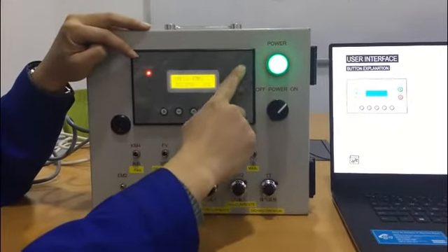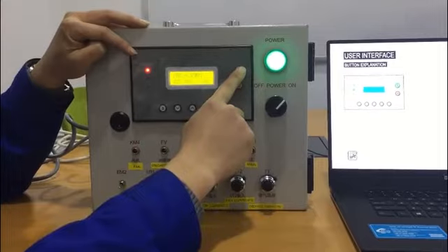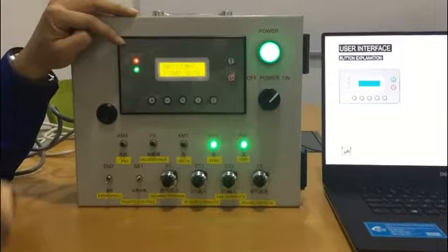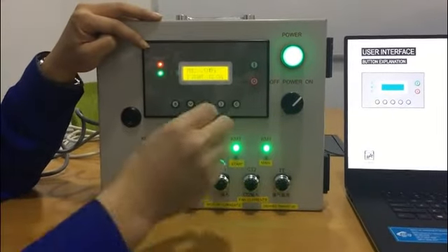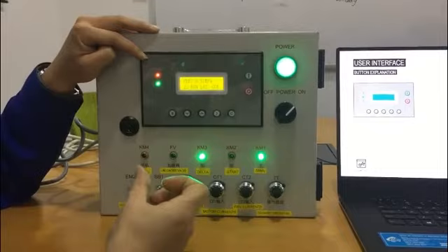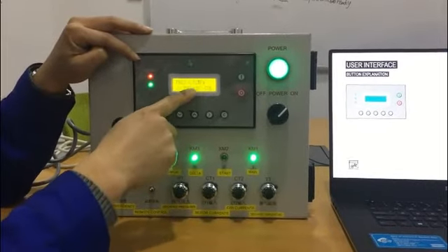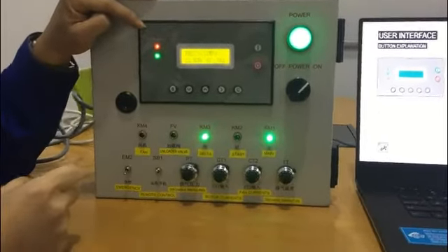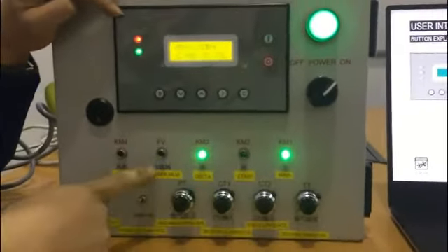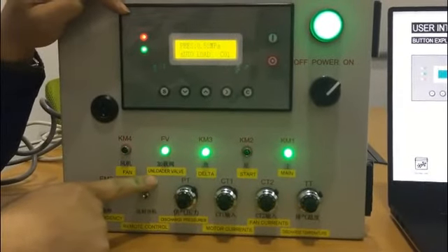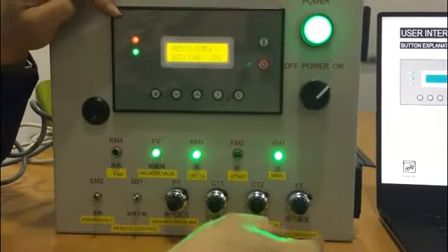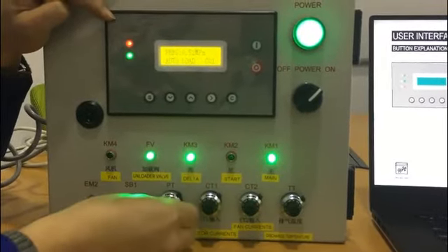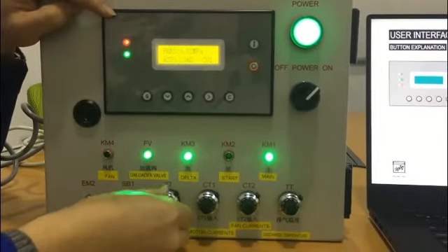And start the compressor. Press the start button. And there are 6 seconds for start delta change, and another 15 seconds for loading delay. Okay, it's in load. And if we turn off this switch, you can see the pressure change.